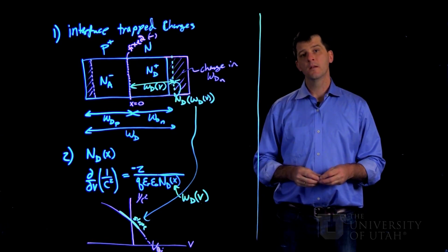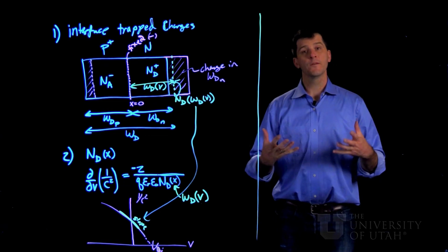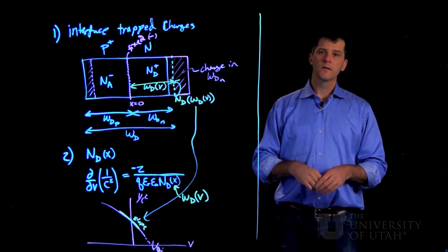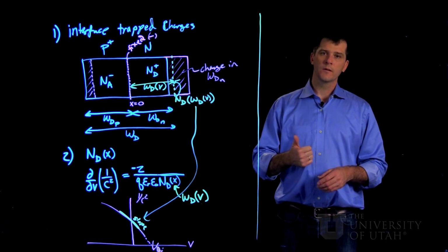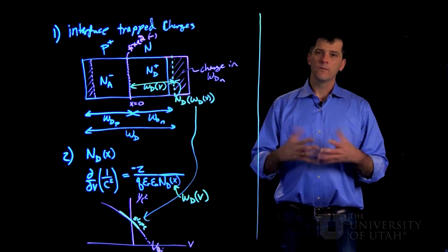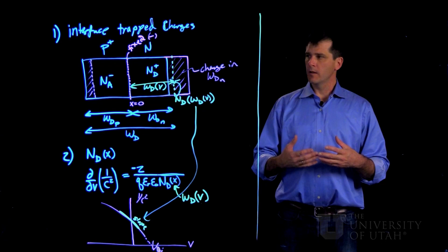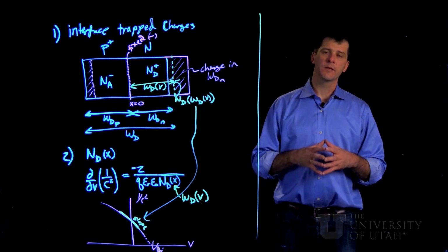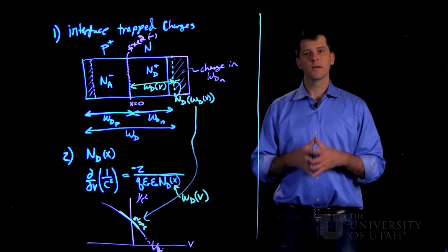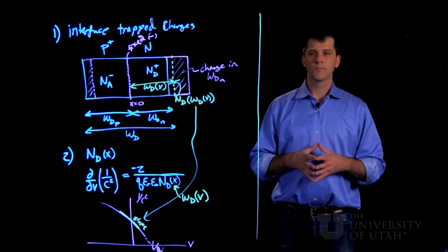We've looked at how the carrier density on both sides induced by the doping leads to a built-in voltage. Then we've come up with a set of 3 equations that link the built-in voltage to the depletion widths. And we've introduced the concept of treating the p-n junction like a parallel plate capacitor to determine the junction capacitance, and then talked about how that can be used to actually measure doping as a function of distance through CV profiling.